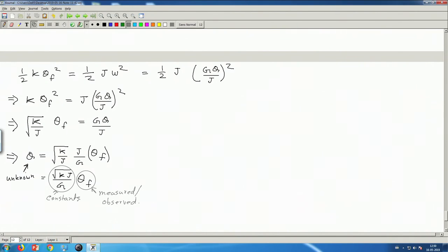Very quickly, let us summarize how we will do it experimentally. We will let the impulse current flow through the coil and then the pointer will start to move and it will start to oscillate. So, if the pointer is initially at its 0 position, and then the impulse current flows, it will set the pointer in motion, it will give it some kinetic energy. So, it will go to some extreme position and then oscillate. We have to measure this amplitude of oscillation.